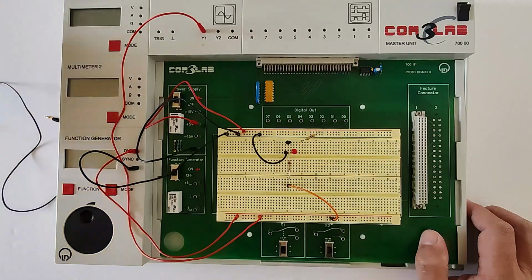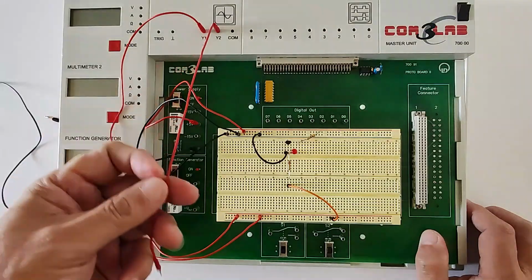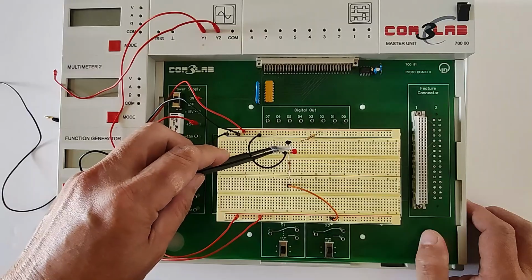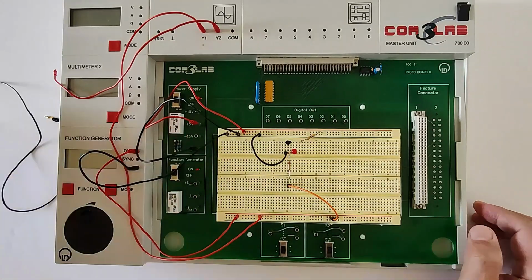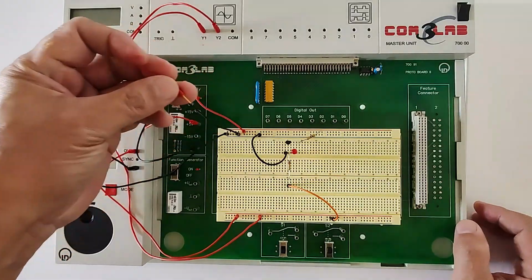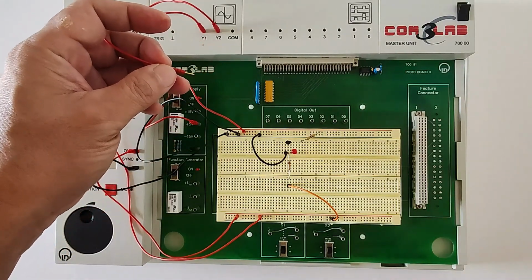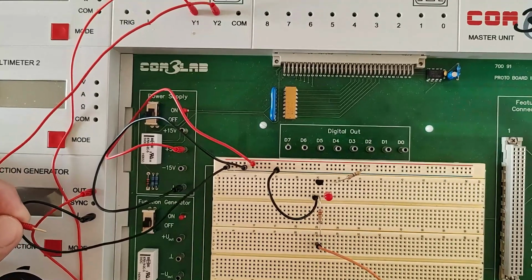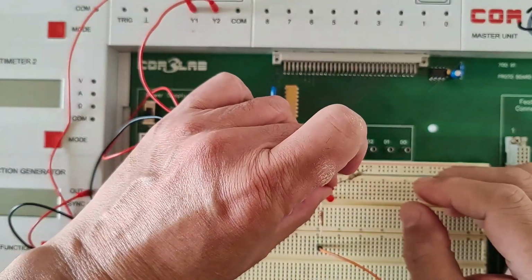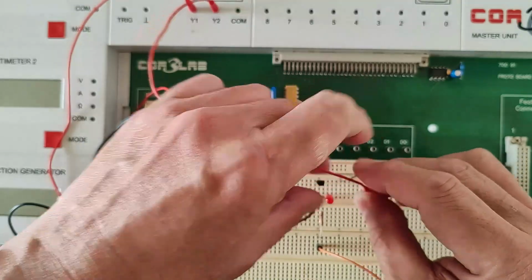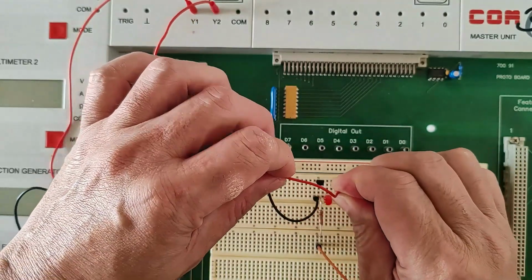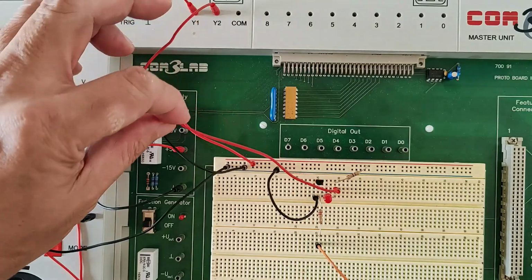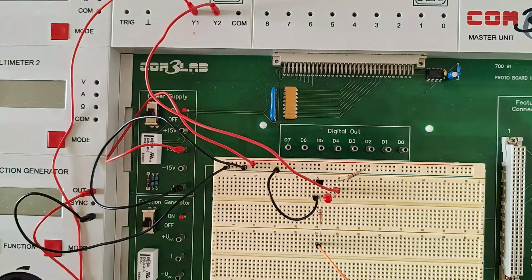Now, for Y2, I'm going to use Y2 for the output. Y2 is the output. Now, output here is that red LED. It's our output. So we're going to use the red LED as the output. So the Y2 cable, this one, will have to be connected to that red LED. Closer look of that one. I have to connect it there on that red LED. Show you. Connect it here, between the red LED and the resistor for the output. There. So between the cathode, same line as the cathode and one of the legs of that resistor.